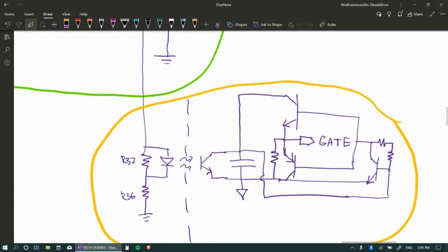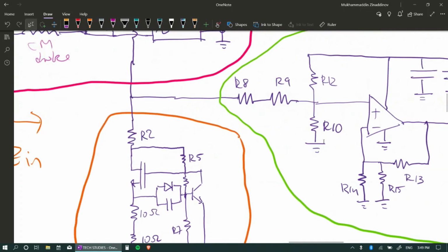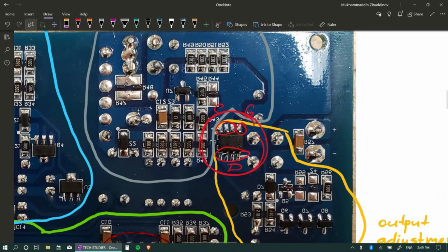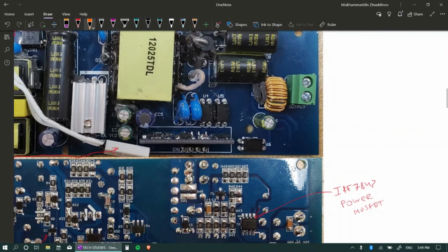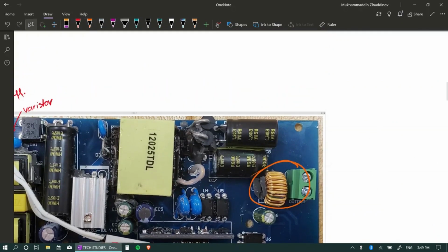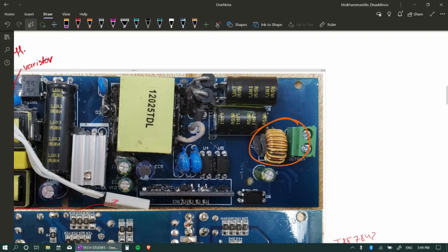That digital signal is then sent to the transistor. This one here is then connected to the output through another choke. Let me show you. It looks like this, and I'll show you the other side, this one. This output choke is also necessary because whatever wires are coming out of here can pick up radiated electromagnetic interference from another source. In order for it not to propagate inside the board from the output terminal, you need an output choke as well.